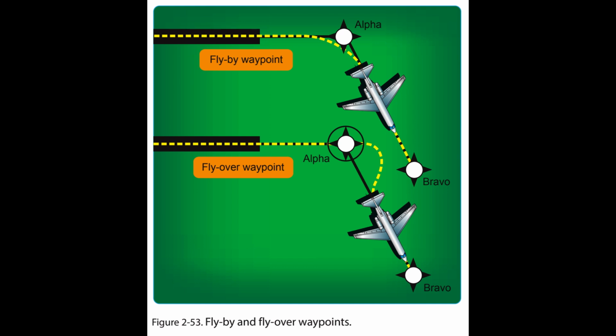An example of user-defined waypoints typically includes those generated by various means including keyboard input and even electronic map mode functions used to establish waypoints with a cursor on the display. Another example is an offset phantom waypoint, which is a point in space formed by a bearing and distance from navaids, such as VORTAC and Tactical Air Navigation (TACAN) stations, using a variety of navigation systems. When specifying unpublished waypoints in a flight plan, they can be communicated using the frequency/bearing/distance format or latitude and longitude, and they automatically become compulsory reporting points unless otherwise advised by ATC.